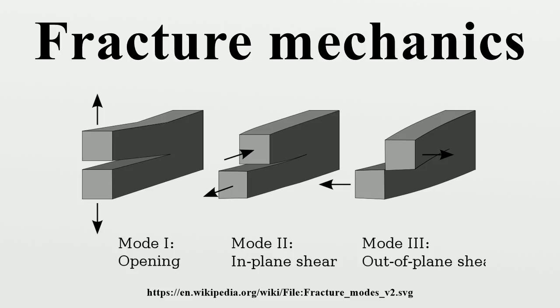JQ theory. By using FEM, one can establish a parameter Q to modify the stress field for a better solution when the plastic zone is growing. The new stress field is given by the modified expression for the region of interest, and 0 if not. Q usually takes values from -3 to +2. A negative value greatly changes the geometry of the plastic zone.